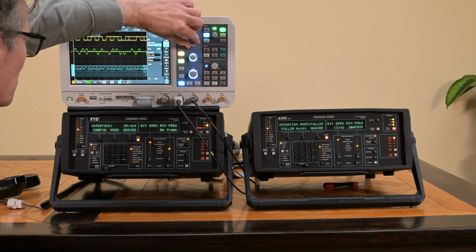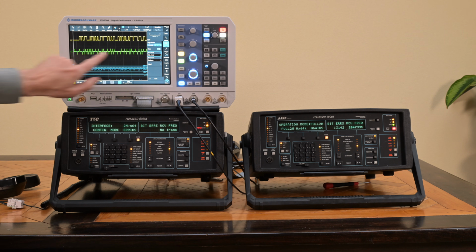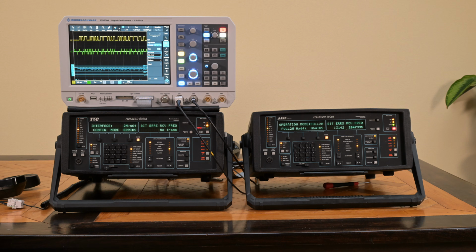It might also be worthwhile to look a little bit at the type of signal that we're getting, because this is the actual data signal, so the raw bits within the device. This is actually the signal going over the trunk line, and you can see it's a rather different type of thing. It's a kind of non-return-to-zero signal. It has a slightly higher frequency, and somehow the information is hidden in here. So that is the type of signals that are being defined for this type of telecom interface. Let's have it running again.